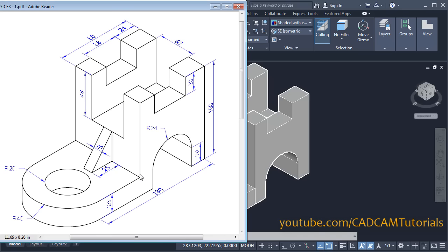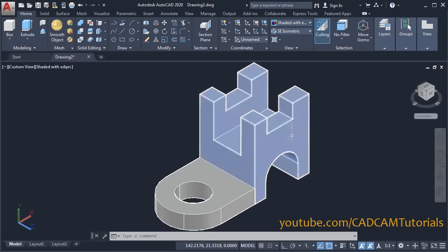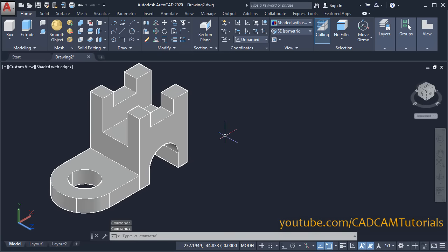Then next is to create this rib of 25 length, then height will be this 100 minus this 48 minus this 20, that is 32. So we will create this triangle of 25 length, 32 height, and our plane is correct, that is XY is vertical. Click on line,